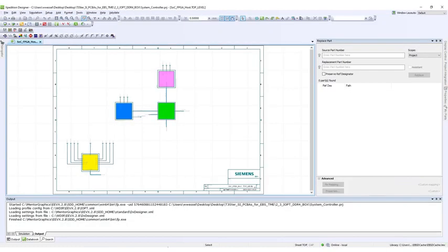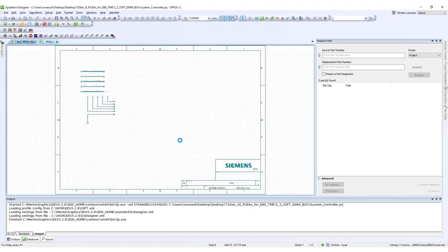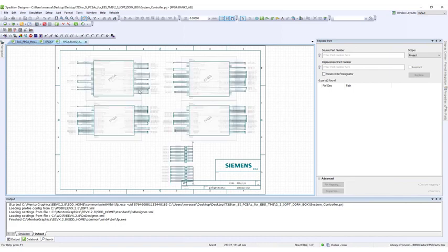FPGA I/O optimization is tightly integrated into the Expedition layout flow. It keeps schematic, layout and the vendor FPGA project in sync by using a synchronization assistant. This assistant has direct access to the central database and to vendor constraints and HDL files.